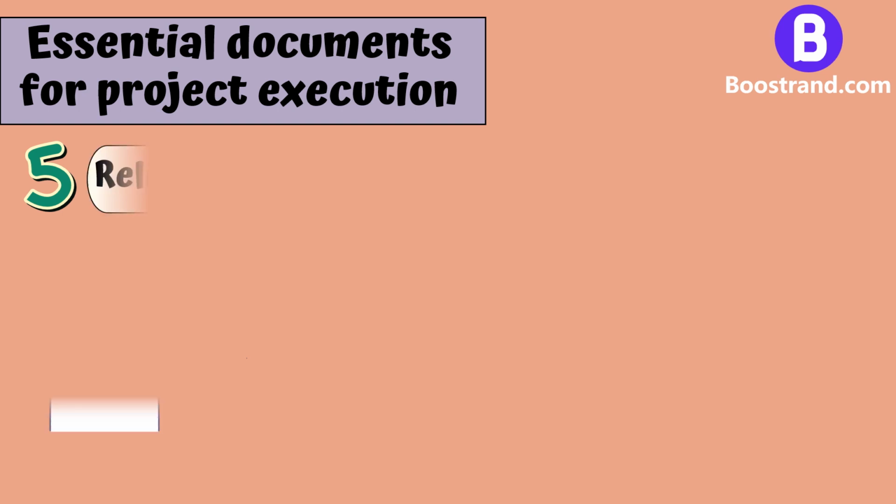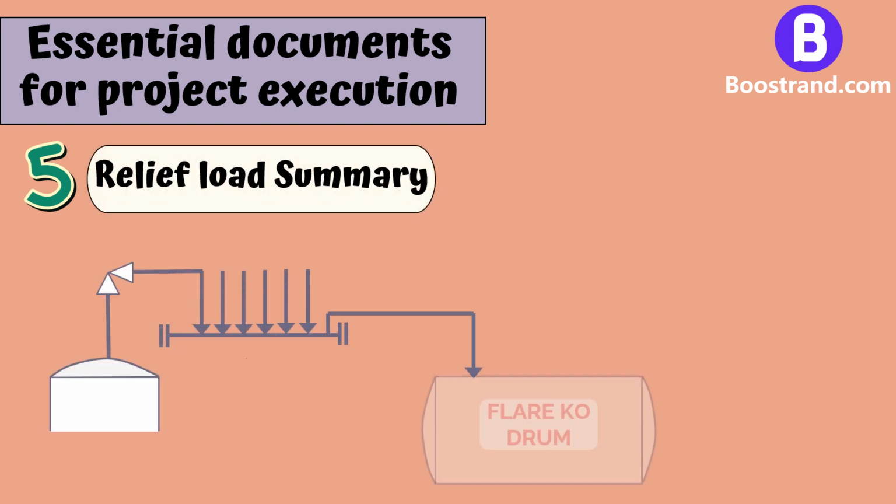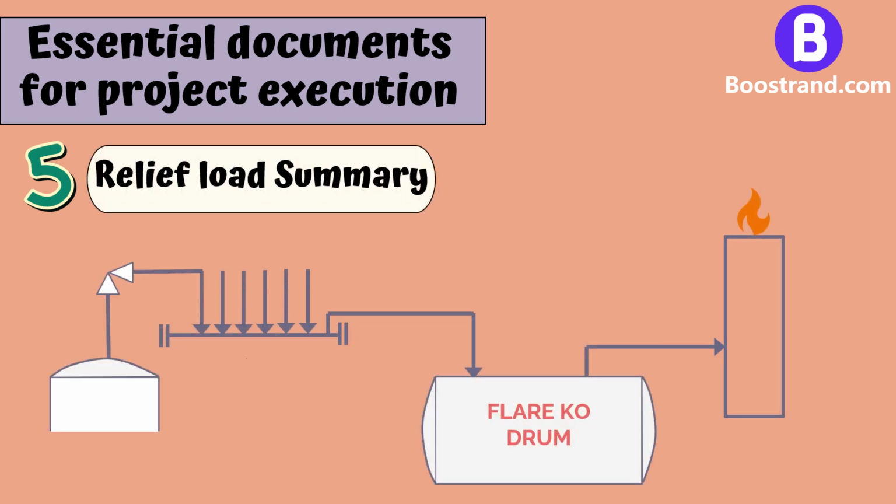In addition, a relief load report is commonly issued by a process engineer. In the relief load summary, all loads from pressure safety valves and blowdown valves are stated, as this shall be the basis for sizing the whole flare system.